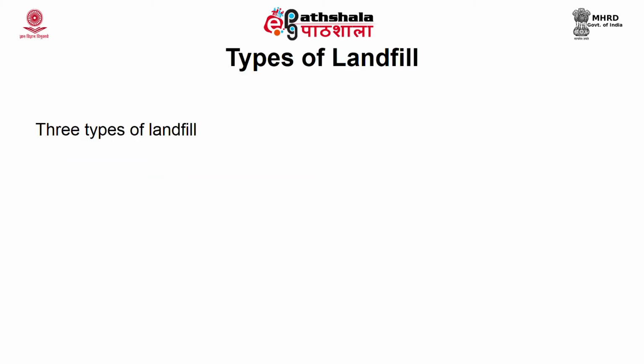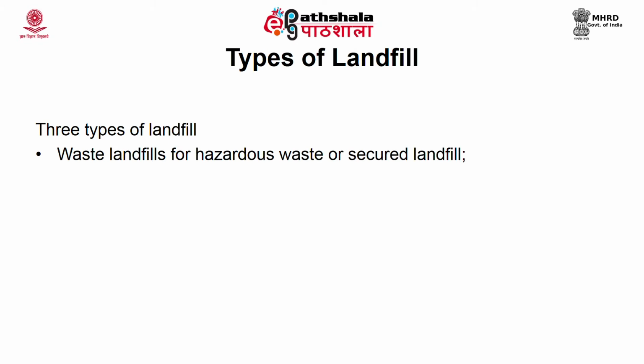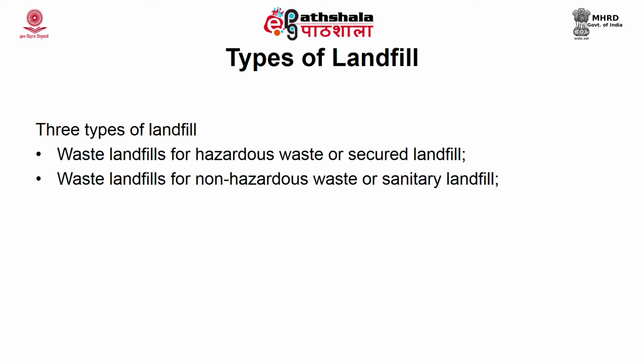Now, coming to the types of landfill, there are 3 types. One is for hazardous waste, which is called a secured landfill. The other is for non-hazardous waste or municipal waste, which is called a sanitary landfill, and the third one is the landfill for inert waste material. Inert waste material consists of bricks, cement, stone, glass, etc. They do not degrade and hence you do not need a high level of protection for landfills where inert waste is to be dumped.